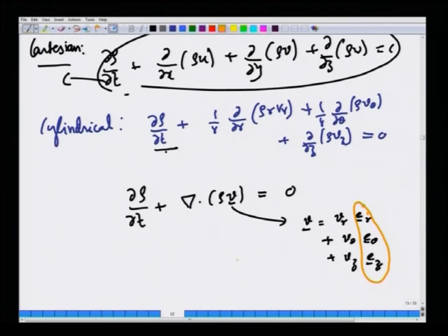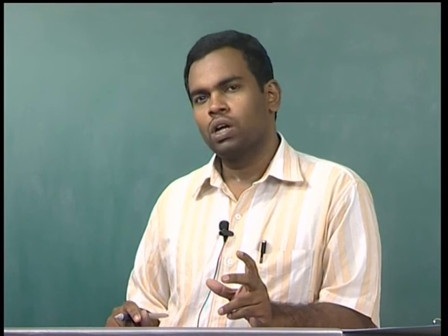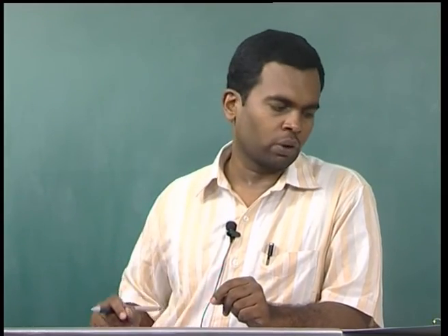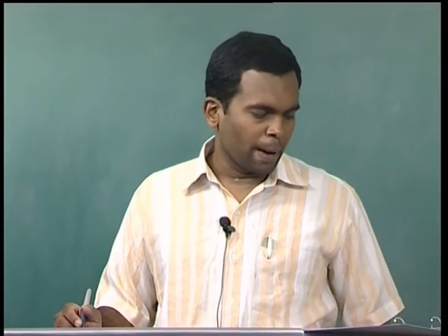When you go along the theta direction, the unit vector Er will change its direction. So, those will also contribute in your continuity equation. That is the simple reason why the continuity equation looks different in cylindrical coordinate system when you compare it with Cartesian coordinate system. Cartesian coordinate system is particularly simple because the direction of unit vectors does not change as you go along a given coordinate direction. That is the reason why that happens.